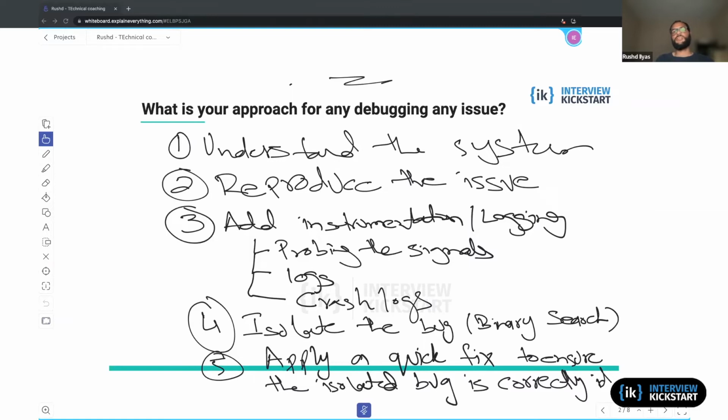Then you will probably be expected to use something like GPIOs to show the state, and you can say, assign these 4 GPIOs to encode the states of the state machine. So again, it depends totally on what kind of system you are on, and what kind of debugging tools it has. Another big one that I haven't mentioned here is tracing, or basically stepping through the code.